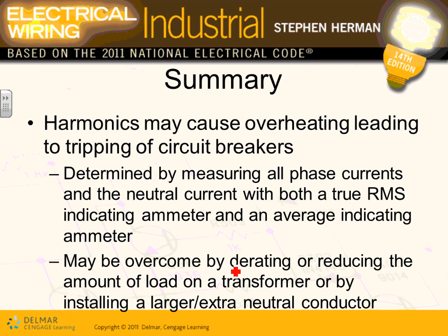Any comments, any questions? The most important thing that we do, guys, when we have a harmonic, especially in data centers, is oversize things. Basically oversize, that's what the solution is. In a severe data center, they have a double neutral. The neutral will be double the phase, 100, 200. And they also have filters.